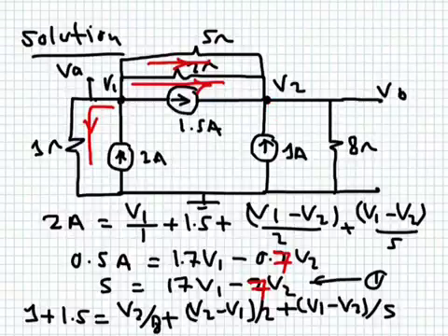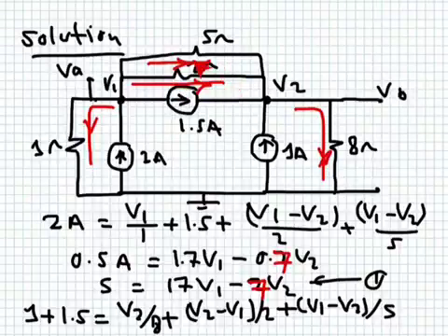So this means that the current flowing in this branch will be flowing from this point to ground, because V2 is higher than 0. And I will assume that we still have these currents in the same direction. I'm not going to change this direction here. So the currents flowing here, I'll keep them in this polarity. The currents flowing this way, I'll keep in this polarity. So these two are also flowing into this node.